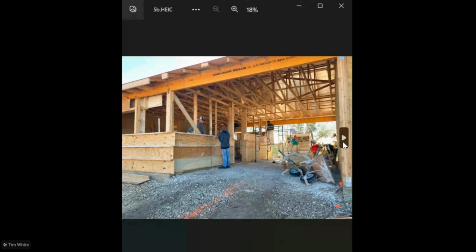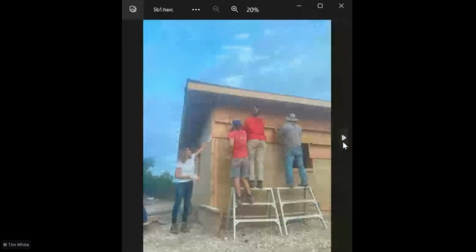Down at the end of the breezeway, we've got the mix and go and our skid steer dumping onto that platform. Somebody pulling it out of the machine if it needs to be cleaned a little bit. And there's little totes right in front of it, so it goes right to them. When you're moving slip forms, using a teamwork approach, teamwork makes the dream work, so that everybody's being safe. I found when they're 16 inches instead of 24 inches, they're a lot lighter and easier for everybody on the job site of all different strengths to be able to help move those forms around.